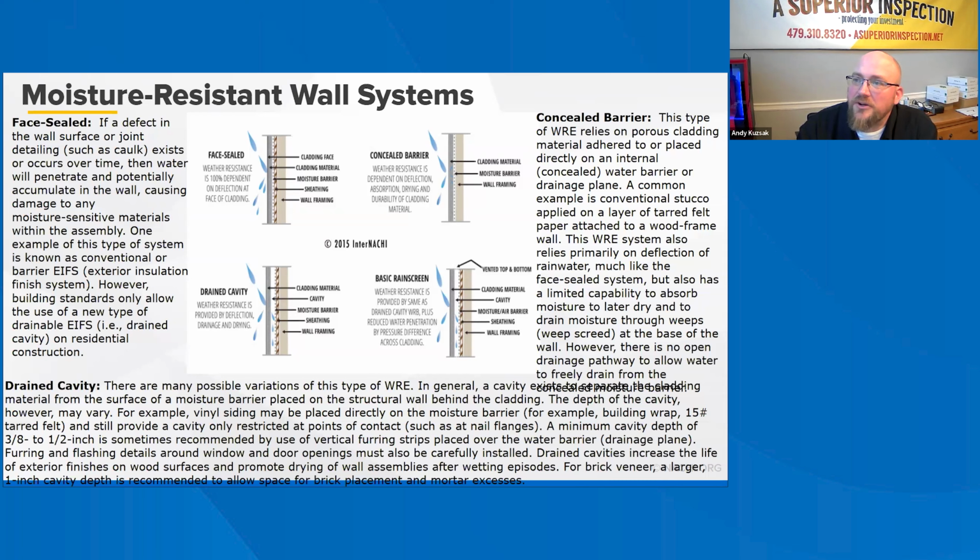Due to the potential for water accumulation within the wall cavity, a water-resistant membrane must be installed behind any exterior siding and veneer. Under certain conditions, it is permissible to eliminate the membrane in detached accessory buildings or where the siding, finished materials, or the lath provides the needed protection. The following 2006 IRC language defines a water-resistant barrier. 703.2, water-resistant barrier: one layer of 15-pound asphalt felt or other approved water-resistant barriers shall be applied over the studs or sheathing of all exterior walls.